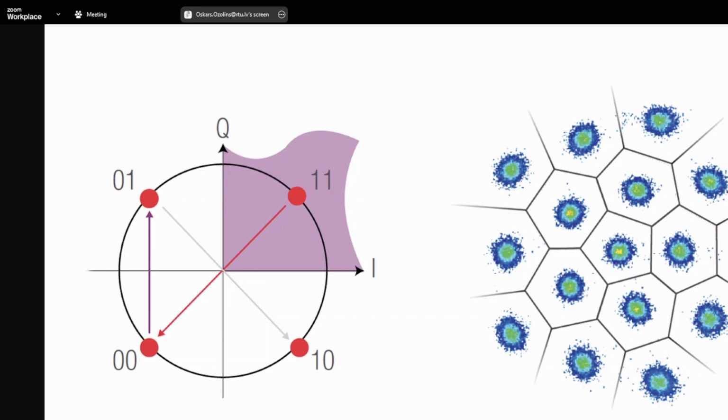And also these cycle slips and phase noise, if the signal is processed in blocks, can result in error bursts. So you can have half of the block with errors due to phase noise. So then you try to avoid these burst errors in blocks. And one more thing is that we can have whatever constellation. Geometrical shaping is possible. So you can define these boundaries as you like.